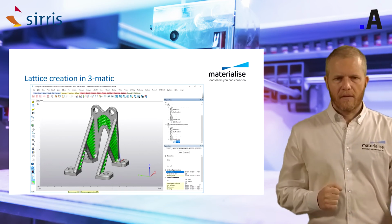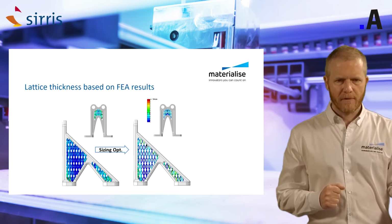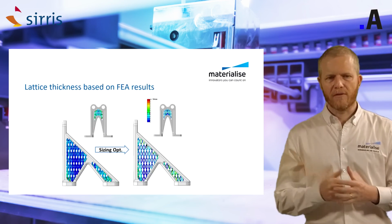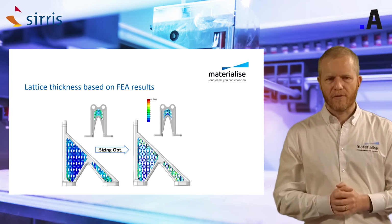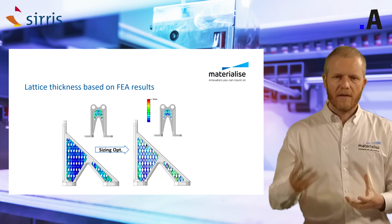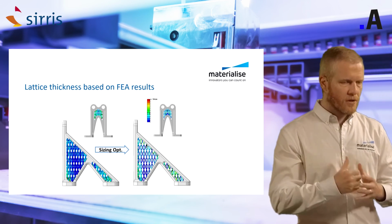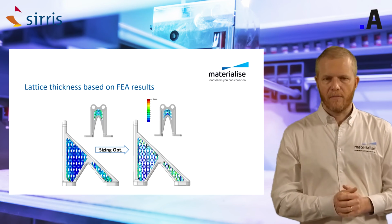In this case, we used FE analysis to change the thickness of the beams. We exported the lattice structure to FEA software, made the simulation in the FEA software, and then imported the results. Based on the results, we changed the thickness of the beams.